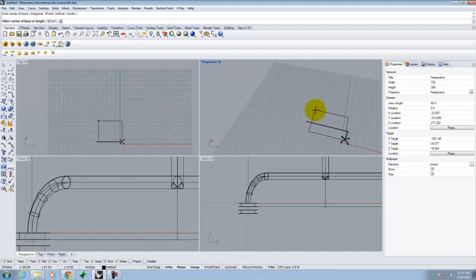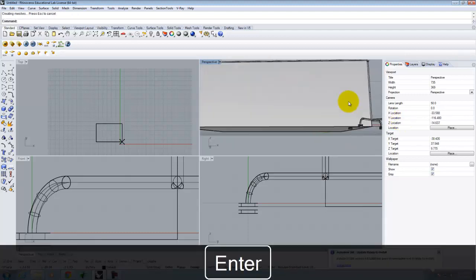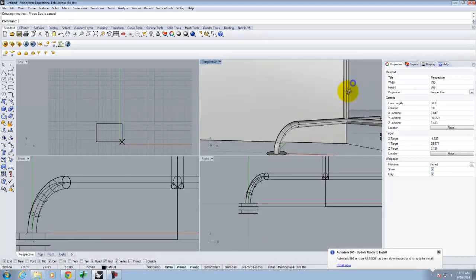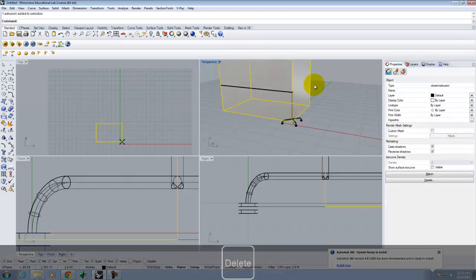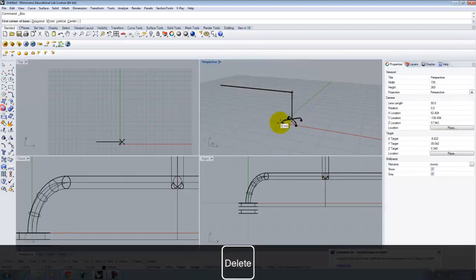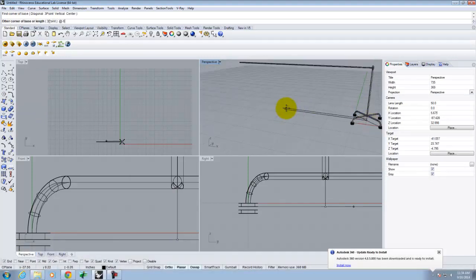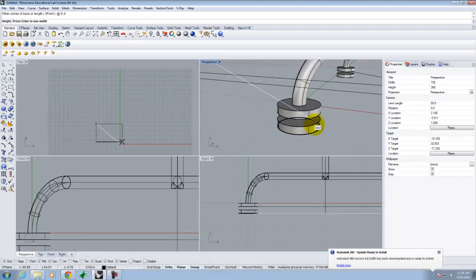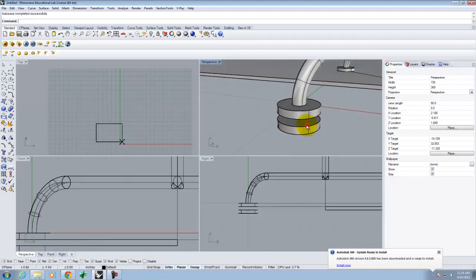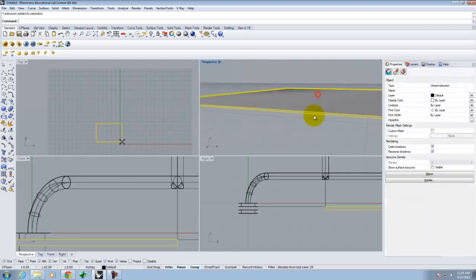At negative 6 feet, comma 4 feet. There it is. And I want my thickness to be equivalent to the gap between these two pieces. And of course, I accidentally clicked. Try that one more time. So we're going to go at negative 6 feet, comma 4 feet. Perfect. And I'm going to reference, hopefully, that right there, create my overall thickness of that piece of glass. So when it's all said and done, I have a nice piece of glass here.